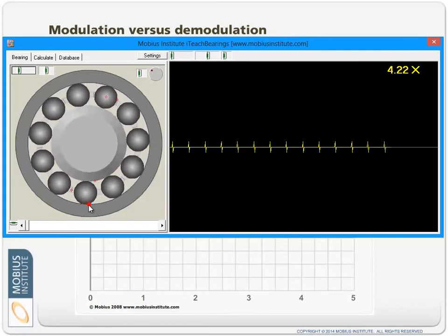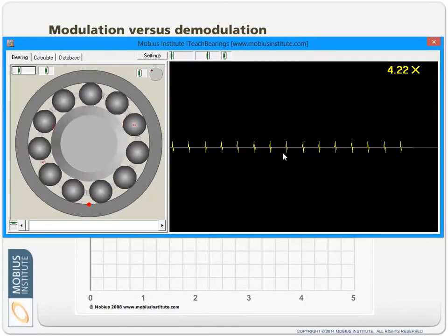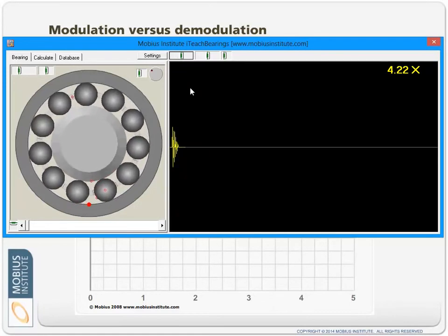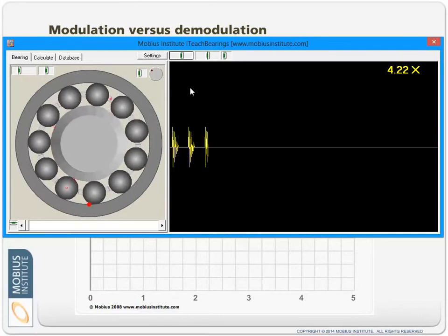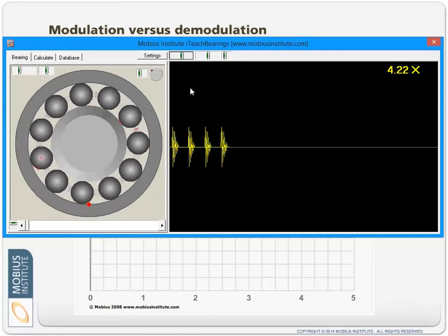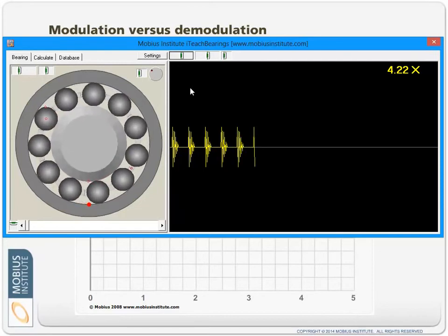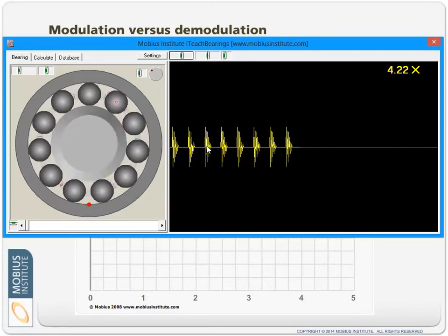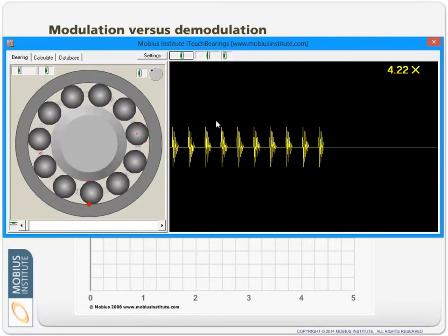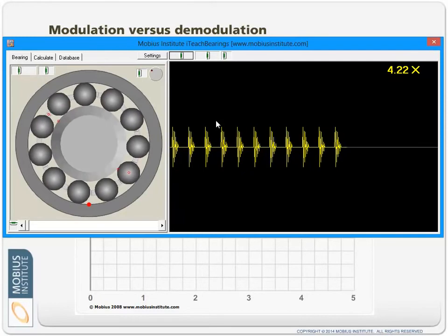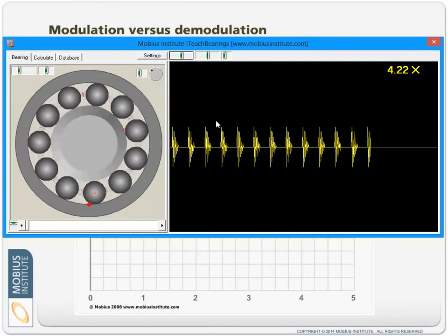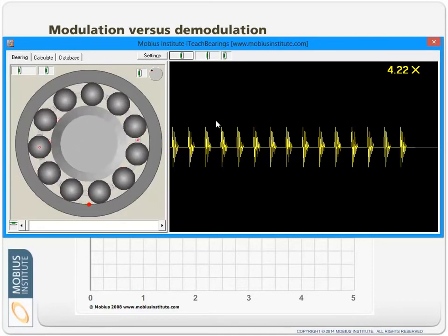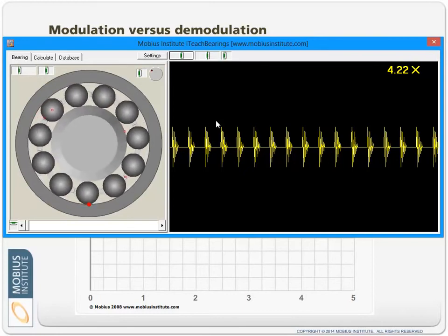And so what we've been left with now is just this waveform. Now what I'm going to do is just increase the amplitude of it so it's a bit easier to see. I've just got ring, ring, ring. Now this is all at a higher frequency source of vibration. What we want to do is make it easier to capture this, because the stress wave or shock wave or the ring could be very short in duration, harder to detect. So we go through an enveloping process or a demodulation process. It's actually the same sort of process that they use in AM radios to extract the sound of the DJ on the radio from the carrier frequency that was used to get it to your radio.